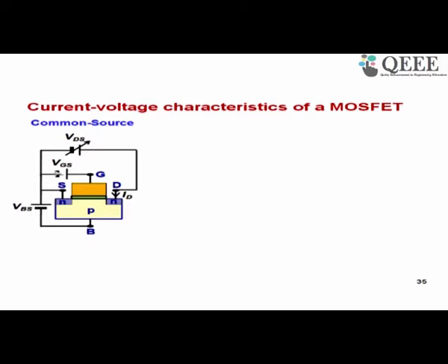So you can see that while a MOSFET is a voltage control device, a bipolar transistor, as we had shown now, is a current control device, but we can show that it can be regarded as voltage controlled also, but a MOSFET is always only a voltage control device. The reason is you have an oxide layer or insulator here which does not allow any current between the controlling terminal, that is the gate, and the substrate. So no current is possible through the control terminal.